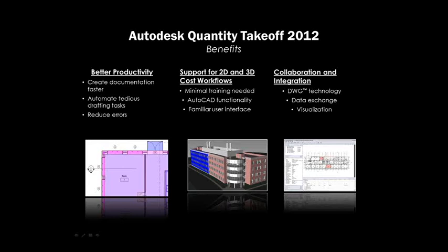One of the things you'll see if you ever implement QTO in a firm's workflow is there's minimal training needed, because the tool is based on an existing engine, which is the DWF engine for Autodesk. For those of you who don't know, DWF is a digital format for viewing plans and exporting your data out of programs like AutoCAD, Revit, and so forth. But it does contain a lot more functionality. Because it's based on the same engine, you'll see a lot of familiar tools, and it's a very light program, so it doesn't have a million tools.